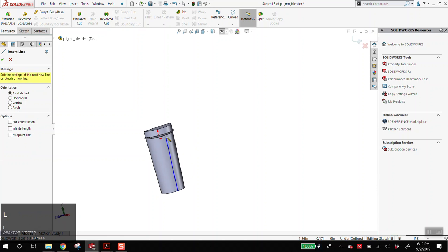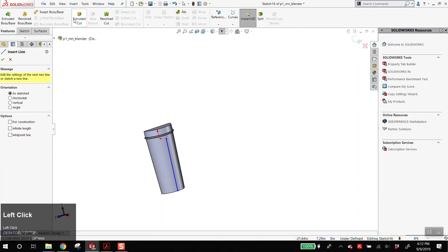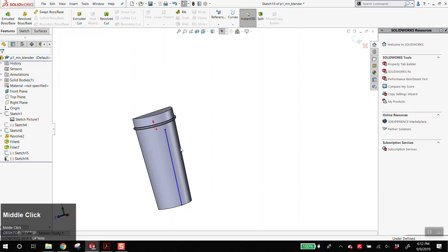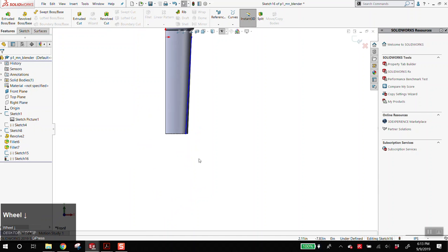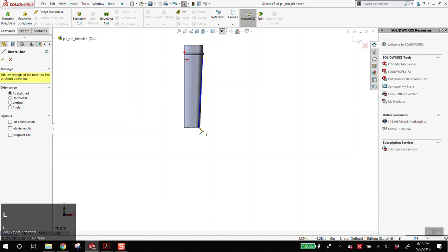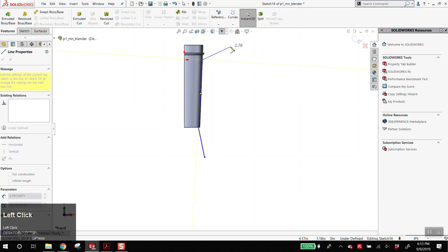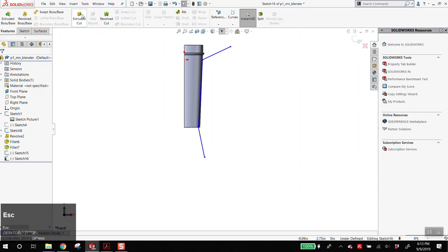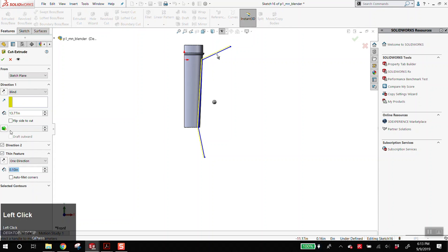I completed the shape, and then I went to features, and I went to extrude cut. I'm going to show you now how to do it without completing the shape. It's the same, but you want to make sure that line goes beyond the object. So you may as well complete the shape, but you can do something like this to make sure it goes beyond the object. You can go to extruded cut. I'm assuming what you had was this thin feature checked.